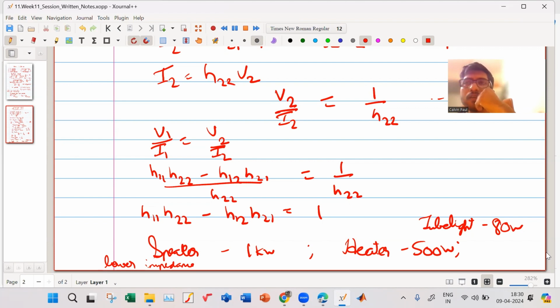Then we should be able to see how much impedance is seen by the device, the load, let us say a processor. The processor is consuming some power, so you want to understand how much impedance it is seeing from the VRM point of view. From the processor point of view, we can come to know where the maximum peaks are. So that is a real case application which I can think of for the Z parameters, right?